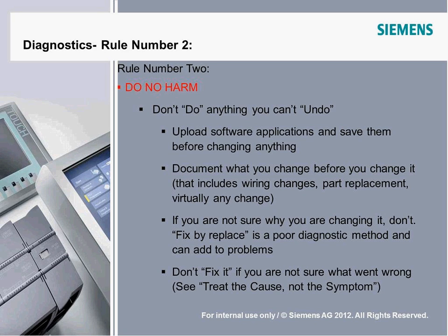And fixing by replacement of devices is a poor diagnostic method, and it actually can cause more problems, especially since it happens a lot nowadays. A lot of things are programmable. A lot of things have configurations. So just taking a spare part off the shelf and sticking it in to replace an existing part may just cause more problems. And so the last point there, don't fix it if you're not sure what went wrong. That's the same kind of idea.